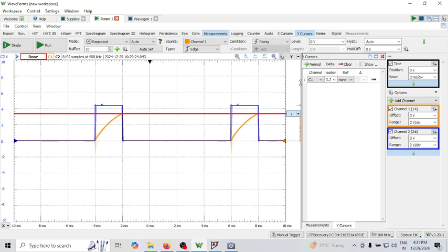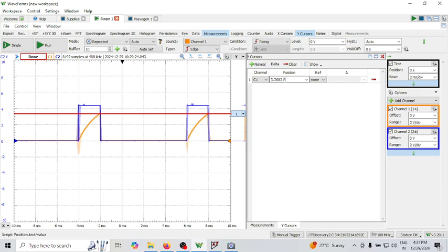Can you see here? This is 3.33 volts, which corresponds to my VTH. So my capacitor voltage reaches VTH, and for this particular setup, I actually have 20K connected and 0.1. So what is the corresponding value of your TPW?